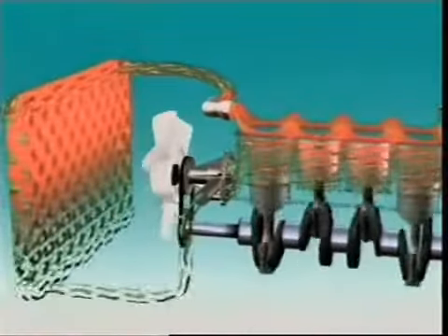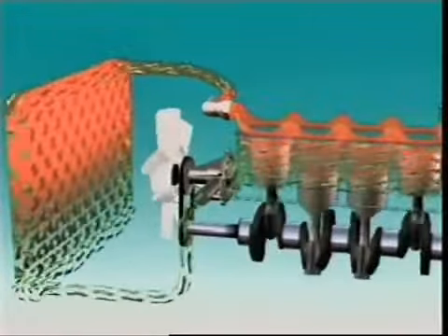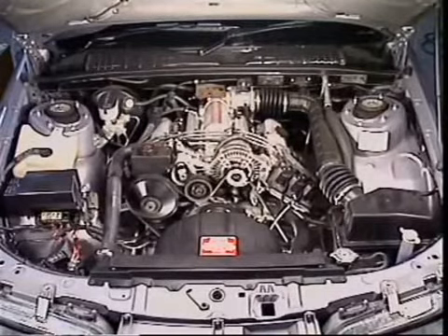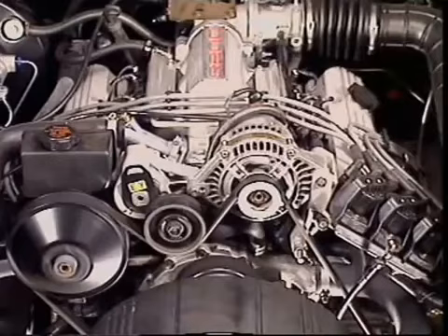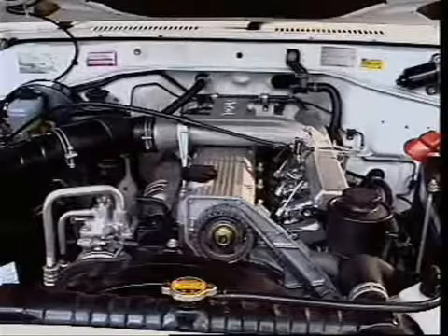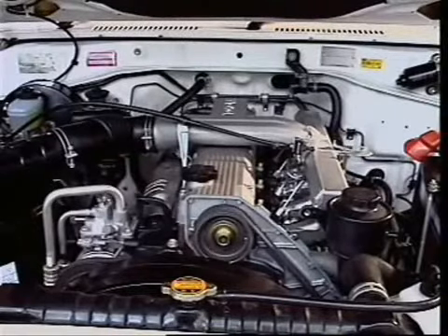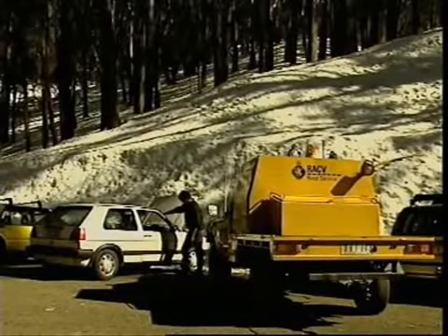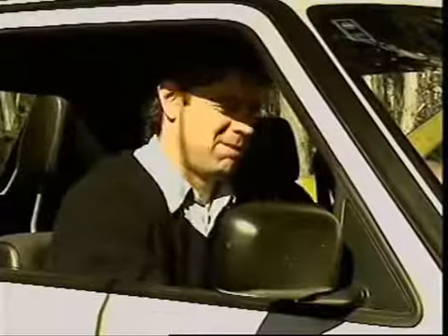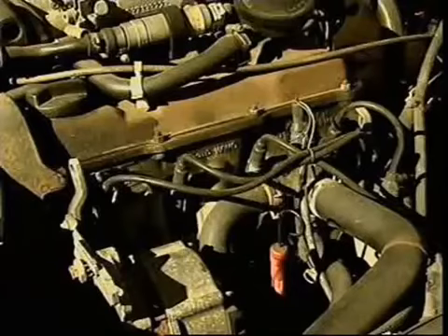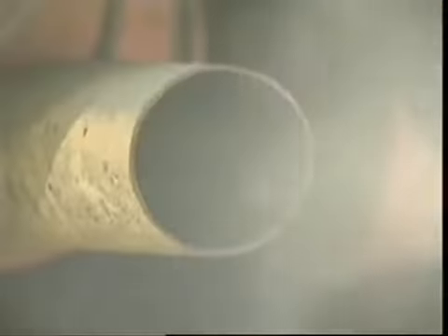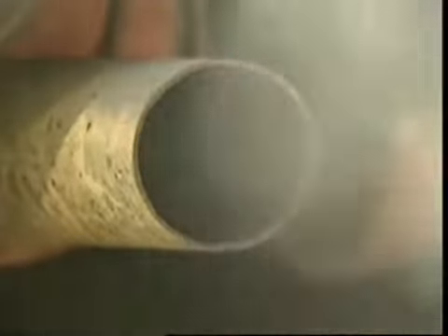Preventing overheating is one function of the cooling system. It also helps the engine reach its best operating temperature as soon as possible. Every engine has a temperature at which it operates best. Below this temperature, ignition and combustion can be difficult. Most engine wear occurs during this warm-up period, and most pollution too.